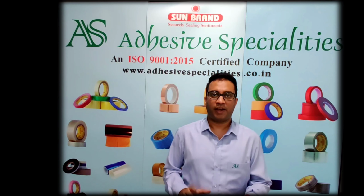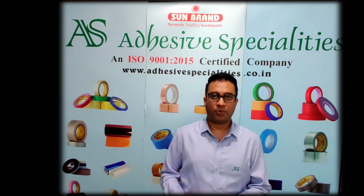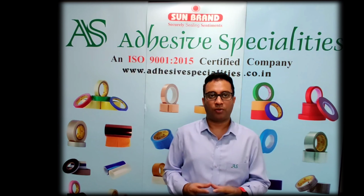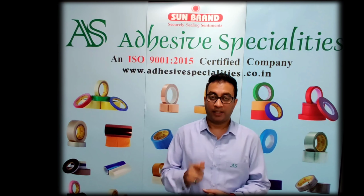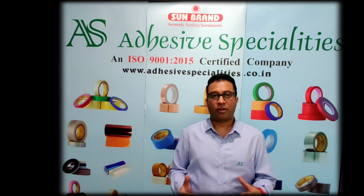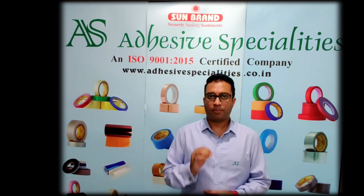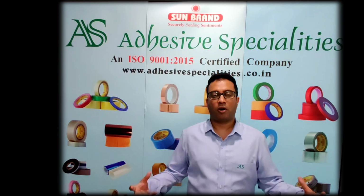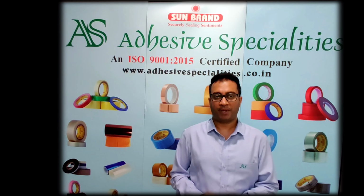Pressure sensitive adhesive is used in the tape industry. Pressure sensitive adhesive forms a bond with light application of pressure. It is a polymeric material, which is a large molecule or macromolecule composed of millions of repeatedly linked units, each a relatively light and simple molecule. So in simple words, a molecular structure of many simpler units bonded together in a chain. So the performance of the tape can be described based on the carrier, the adhesive, or a combination of the two together.